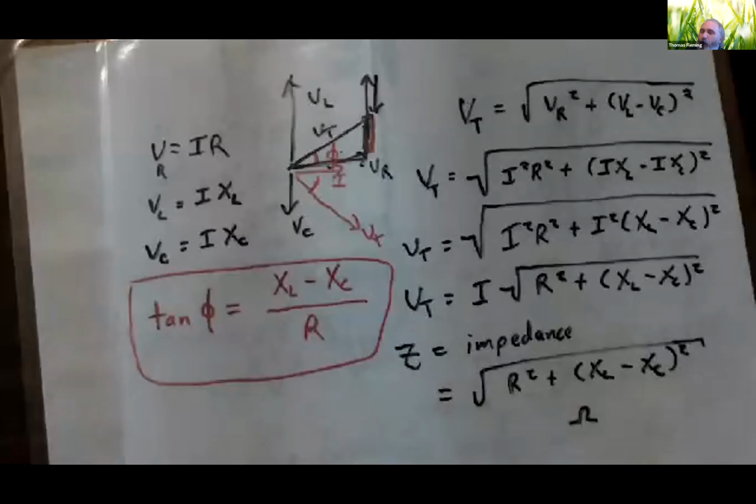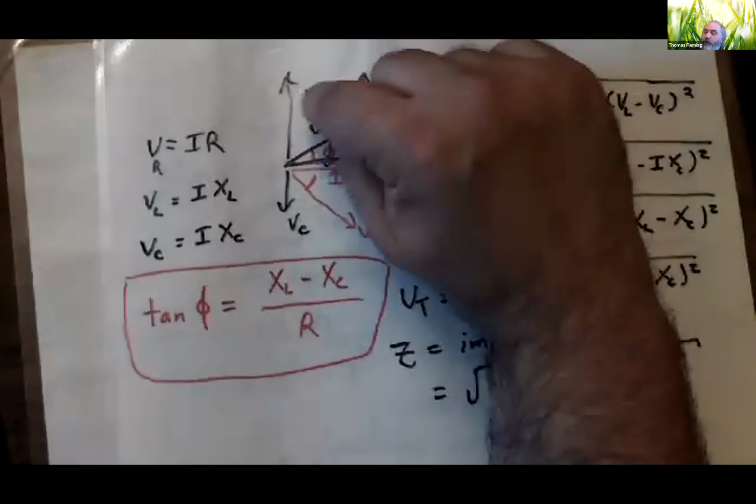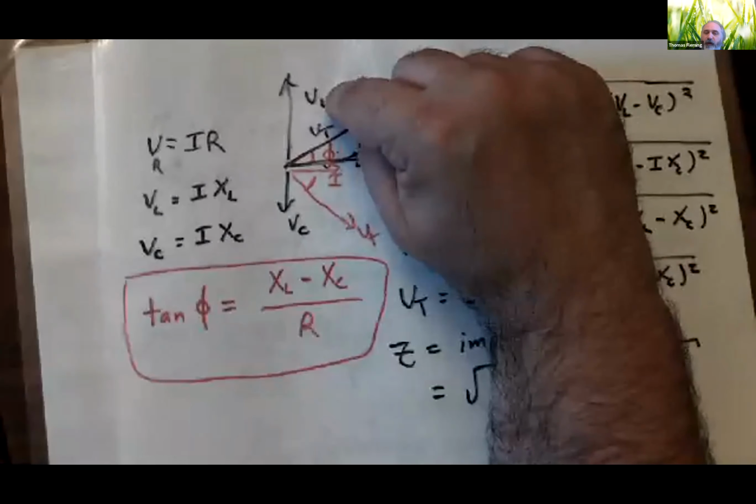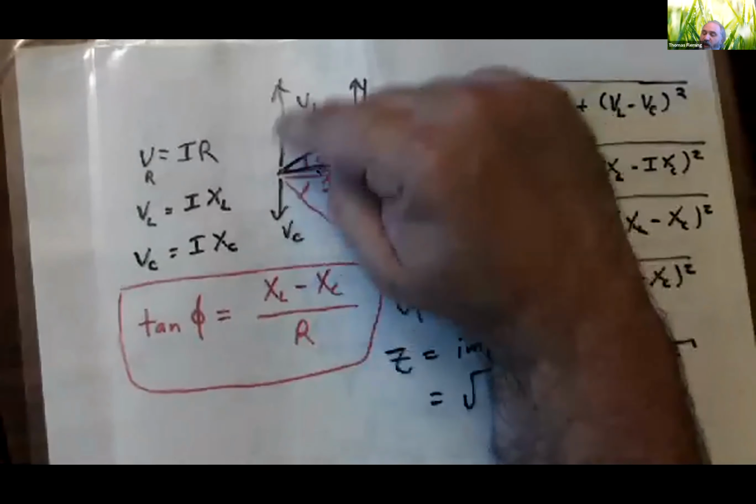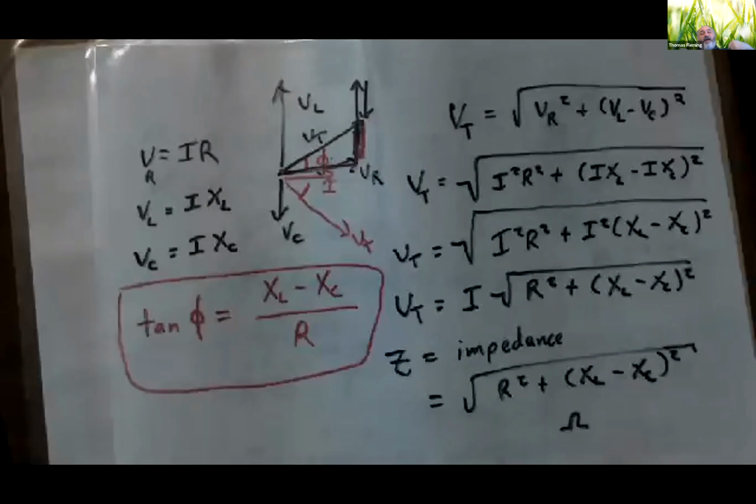So one way to think about what's happening there is, when you're at the resonant frequency, your inductor is always trying to push current one direction, but your capacitor is always 180 degrees out of phase with the inductor. So it's like those two voltages are fighting against each other. And if you're out of phase, it means that one of them is fighting harder than the other one. But when you're at the resonant frequency, the inductor and the capacitor are both trying to push current the opposite way of one another, but they're also fighting equally hard, and they exactly cancel out. And that's what results.